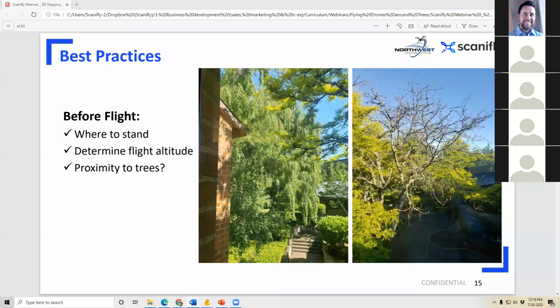Now for the context flight, or the higher altitude flight, the best position is wherever you can keep your drone in your line of sight. We're most likely not going to be able to follow its flight path on foot because of the large diameter of the flight path and obstacles such as other properties or foliage that it'll pass through.